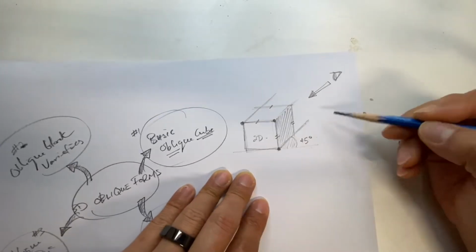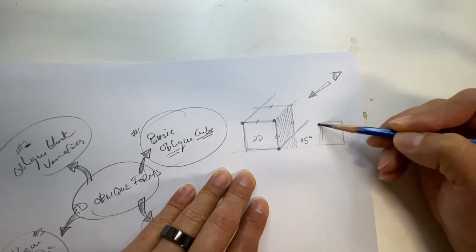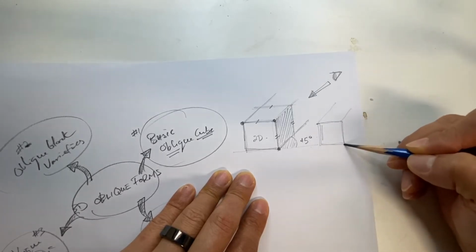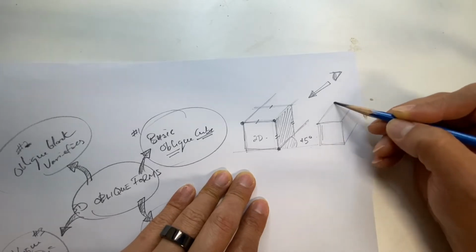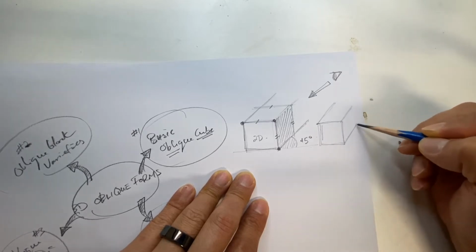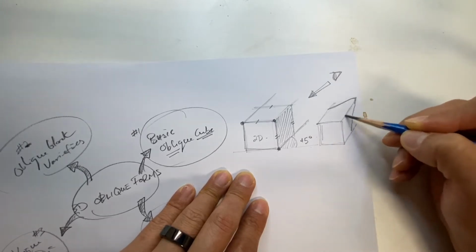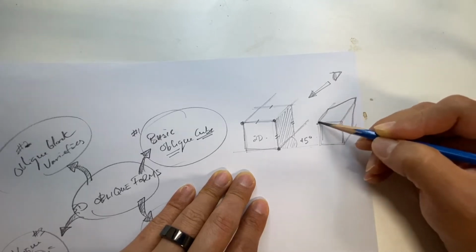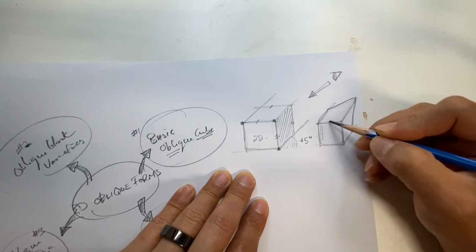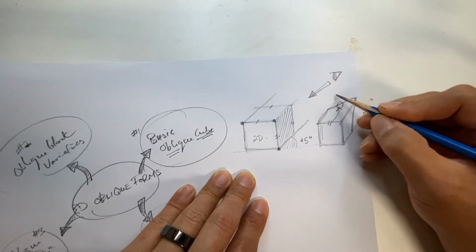Now very often when students draw an oblique drawing or a 3D object, most students will be able to manage the parallel lines at 45 degrees very well. But when it comes to the back, most of them will have problems and you end up with things like that. You get a very funny, weird looking object because you see this line here and this line, they are not parallel.